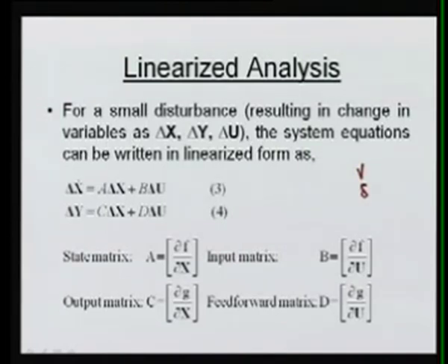For example, if you know V and delta at each bus, and you know the topology, the network configuration, and their parameters, which are fixed, we can calculate all the quantities like P loss, Q loss, the power flows in all the lines, and the reactive power flow in all the lines. These are the things we require in any power system. We can also calculate the reactive power generation at all the buses, especially at generators.